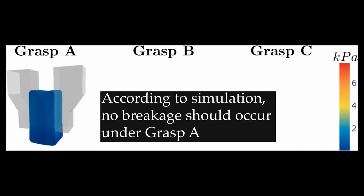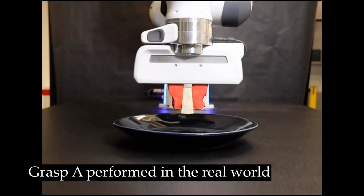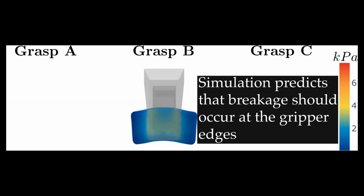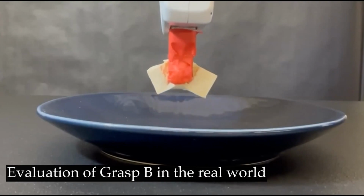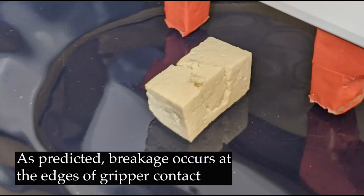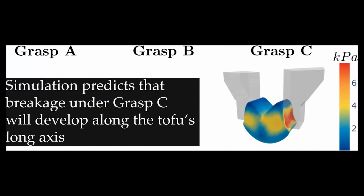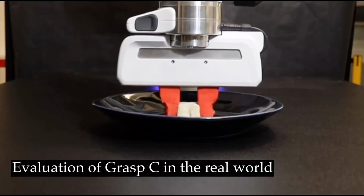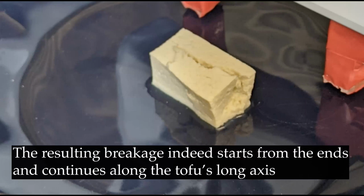Under grasp A, all stresses are below that threshold. And indeed, no breakage occurs. Under grasp B, there should be breakage that occurs at the gripper edges where stresses are higher. We see that breakage indeed occurs along the edges of the gripper. Under grasp C, breakage should occur along the tofu's long axis. And that's exactly what happens in the real world too.